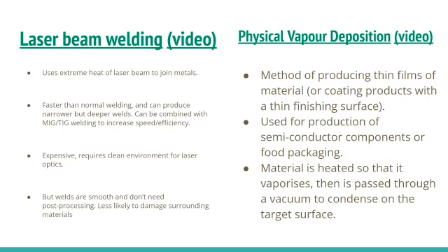It can also be combined with MIG and TIG welding, so you can laser weld it first, and then for extra security, you can MIG or TIG weld the surface of it, and that will give you a very, very strong connection.